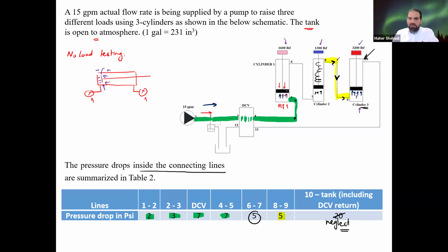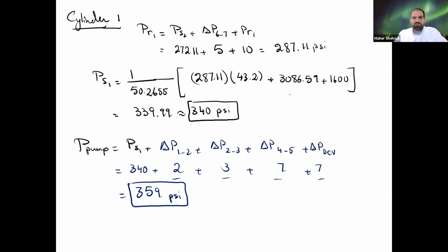Okay. So cylinder 1, the back oil is moving at the same speed as the speed of the oil in front of the piston in cylinder 1. But this oil now leaves with this speed and it feeds this cylinder. So now that speed, V1 times the cap area of cylinder 2 will be the speed of piston 2. We can find then the speed of the oil in the back of cylinder 2, and that's the flow that goes into cylinder 3, and so on. Let's see those in terms of numbers.